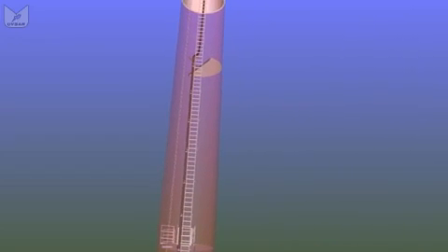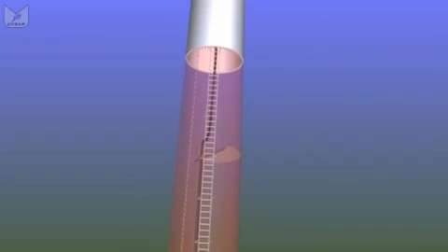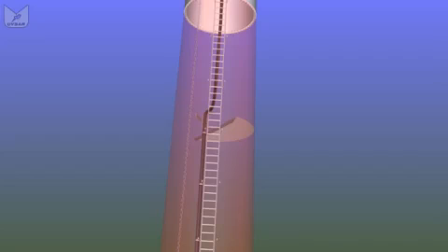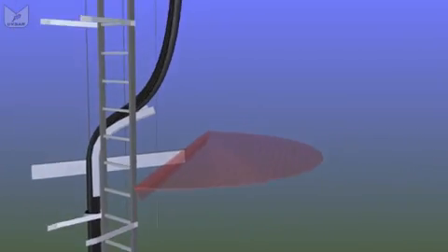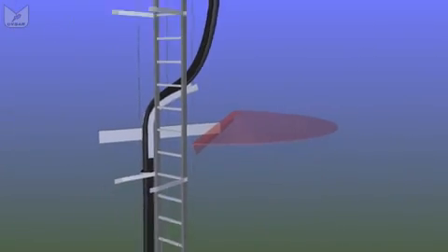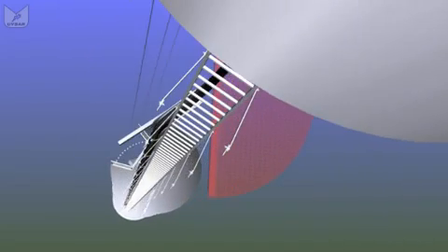And again, the tower's in sections so that it can be delivered around the country without demolishing villages. Sometimes, if we're running a long distance and we haven't got room for a proper platform, we can put a half moon in place. No fall protection on the platform, but we assume you would keep your lanyards connected at this point because it's quite a long way down.